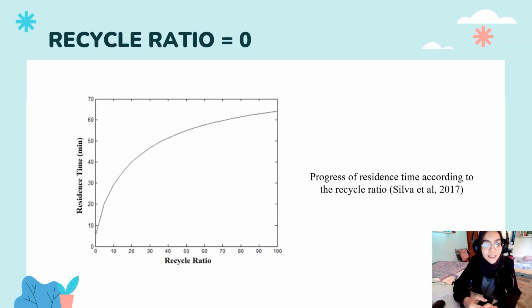The first factor is the recycle ratio, which needs to be 0 because the recycle ratio affects the selectivity and yield of biodiesel, where rising recycle ratio reduces the chemical conversion of our biodiesel production. In this context, high conversion in PFRs can be achieved with minimal residence time at a recycle ratio equal to 0, in order to obtain almost 98% conversion into the biodiesel products, mainly ester.